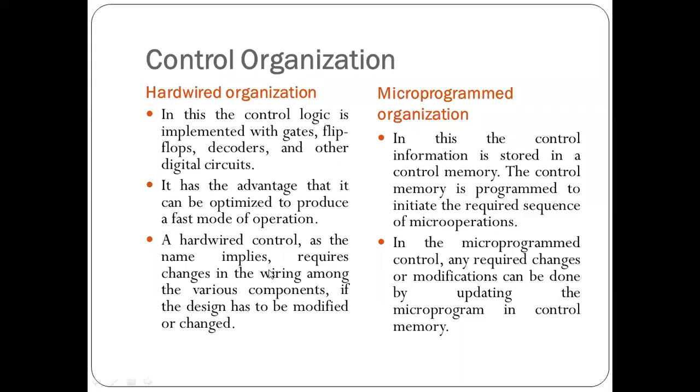If you want to make any updates, or add one more extra instruction in your ALU, then the respective control signals have to be updated. For example, initially I have assumed that my ALU can perform 8 operations. So my control sequence will select 1 out of 8 operations by using 3 control inputs. So I will use a 3 to 8 decoder to select one particular operation.